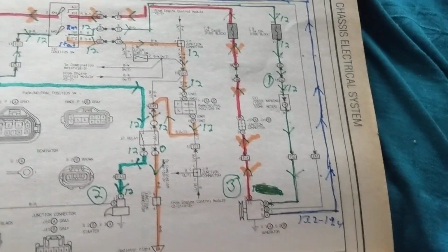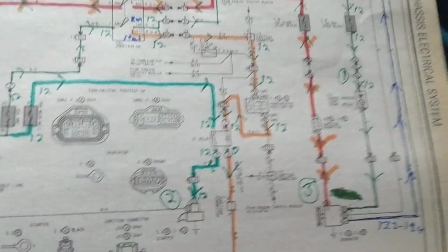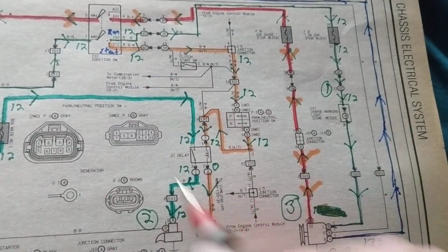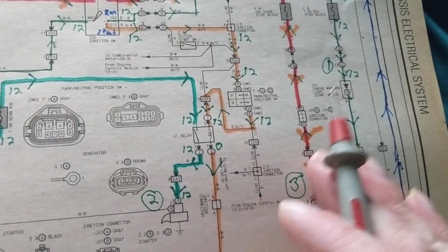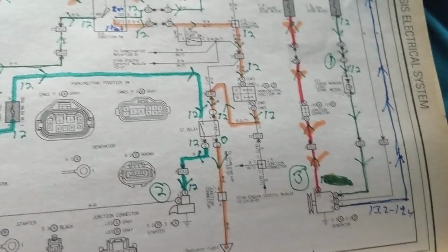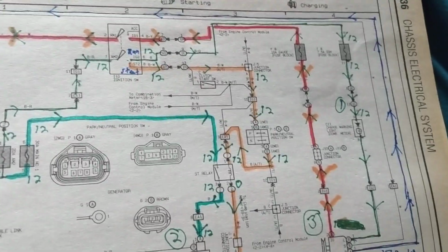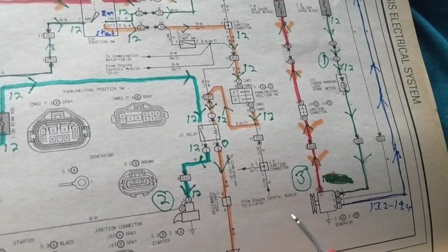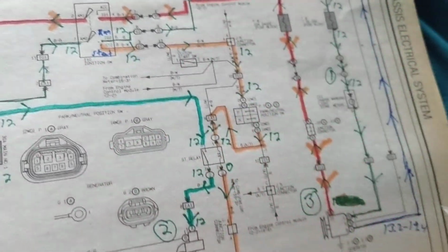Now, in the run position, what happens? In run position, let's say for GMs, the car does something called initialization checks. It checks all the parameters, and it checks also the communications. Let's say the PCM or the BCM, it makes sure that the computers can communicate with each other. If, for whatever reason, the modules, as they're referred to, cannot communicate with each other, you will not start the car. You'll turn the key, but nothing will happen. The computer will not allow you. This is what happens in the run position.